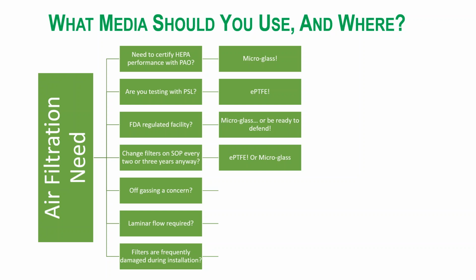Change filters on SOP or every 2 to 3 years anyway. Really doesn't matter in that case. You can use either or. Just again, PTFE is going to be a lot more expensive than microglass. So if you're going to change them out, you should probably be cognizant of the cost as a result of that.